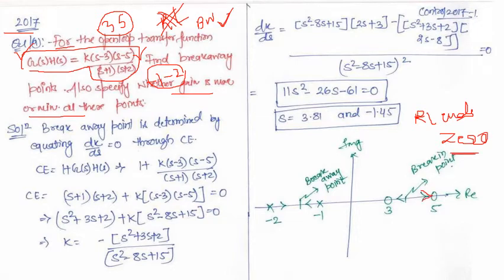So you can see I am drawing the arrow directions ending towards the zeros, and the root locus exists between -1 and -2, and the direction of arrow is different because root locus starts from the open loop poles. Okay, root locus starts from the open loop poles, and that's what I am drawing here, the arrow direction outward. Okay, it cannot go in this direction because there is no root locus which exists between 3 and -1. Similarly, -2 onwards till infinity, there will not be any root locus.